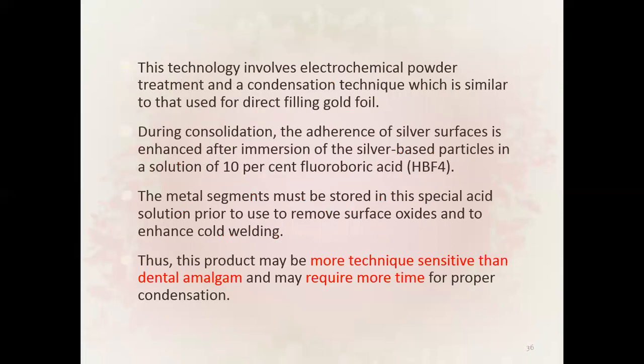This technology involves electrochemical powder treatment and the condensation technique, which is similar to that used for direct filling gold foil. During consolidation, the adherence of silver surfaces is enhanced after immersion of the silver-based particles in a solution of 10% fluoroboric acid.